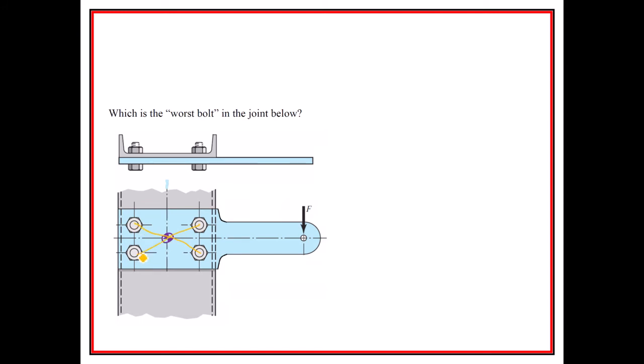So if I decided in here to call this one A, this one B, this one C, and D, right? And so this is RA, RB, RC, and RD, that diagonal distance from the bolt center right here. And so if we apply the moment that's going to be generated by this, it's going to create a moment where we have FA double prime.